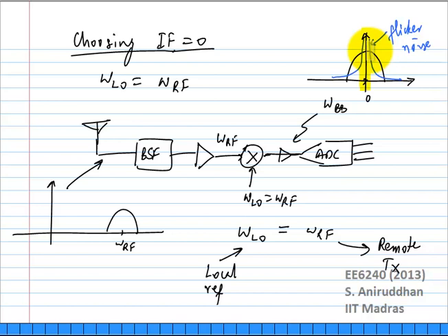Exactly. Another option is to just couple it out using a series capacitor. The only thing is the capacitor will need to be huge, because the relative frequencies you are talking about here are very low. The capacitor will need to be really large. That is another way of doing it.